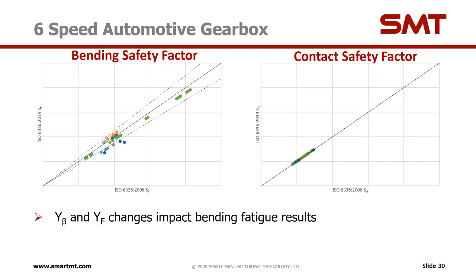The biggest reduction that we see here is due to helical gear with overlap ratio less than 1 and virtual contact ratio less than 2. The general trend is similar to that we actually discussed for individual sets before.